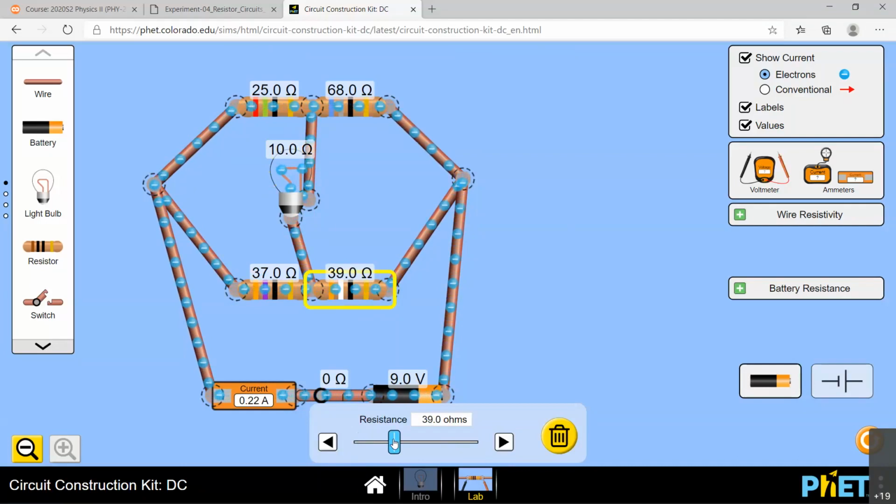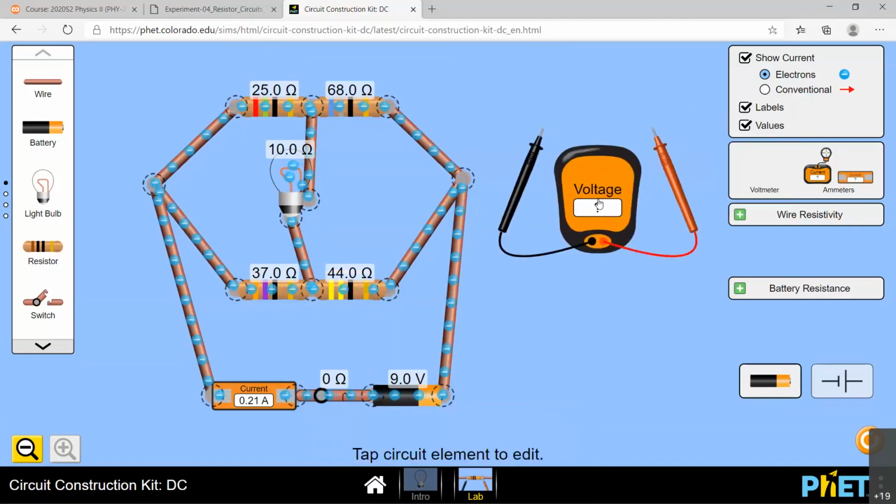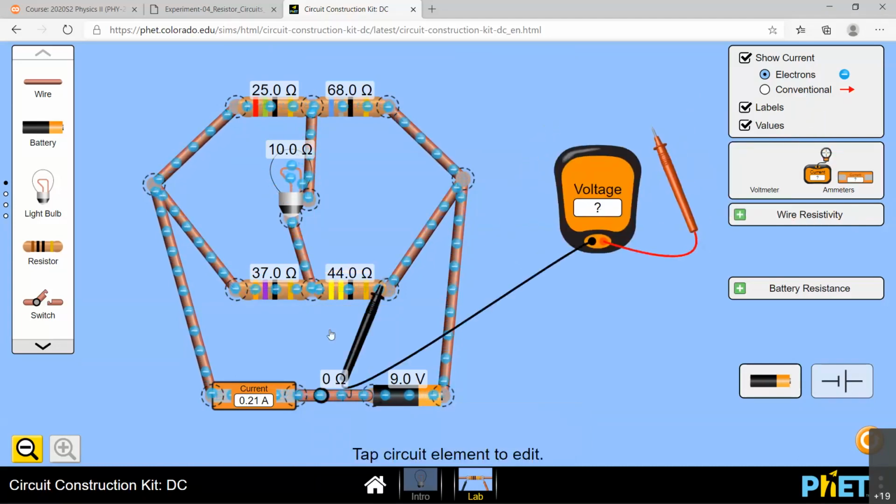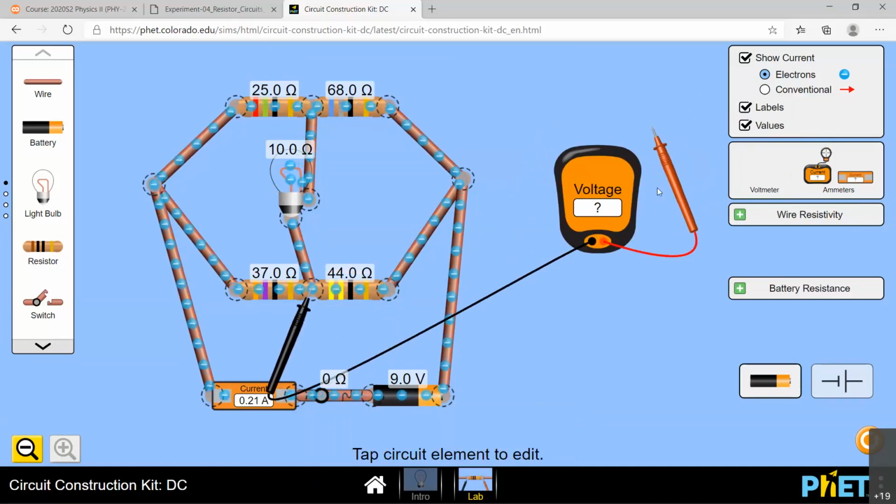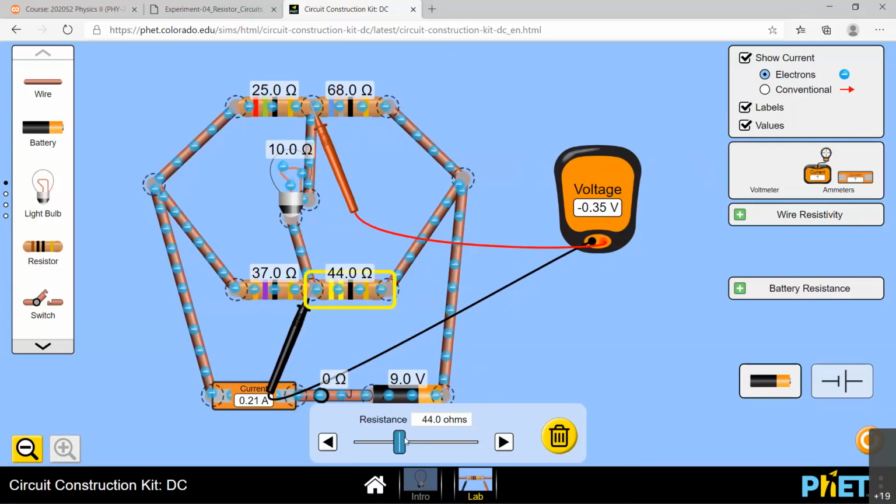Now you can see the electron passing through that line becomes slower and slower. At some point, that yellow line around the light bulb almost vanishes, right? But I can't see the exact point. The good way to measure that is to bring a voltmeter, put the voltage probes on these 2 points, measure the voltage, and then change the resistor R4 until you see exactly 0 voltage, right?